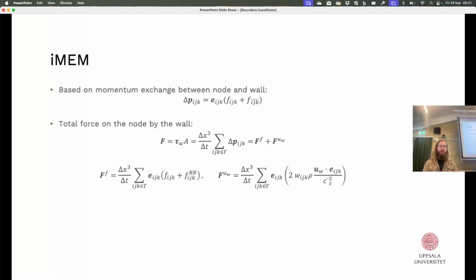And I really think that this is a very good idea, and one that is very compatible with lattice Boltzmann, actually. After having reviewed also the others, I think this is one of the most LBM intrinsic. And it is independent also of the collision operator. And you don't need an omega near the wall, because we use turbulence models also, so we're going to talk about this later on. So the whole question of omega near the wall, the relaxation frequency near the wall, is a bit difficult, I would argue. So this is absolutely independent.